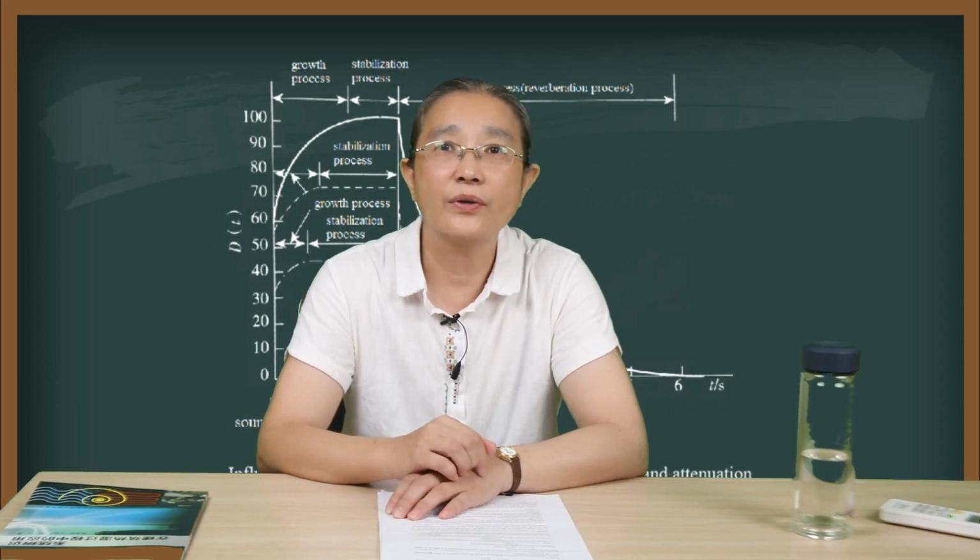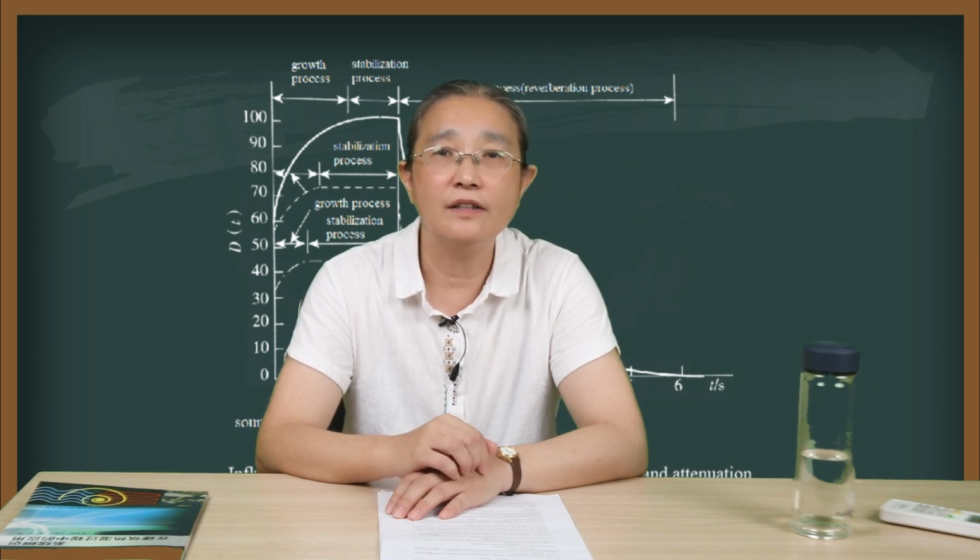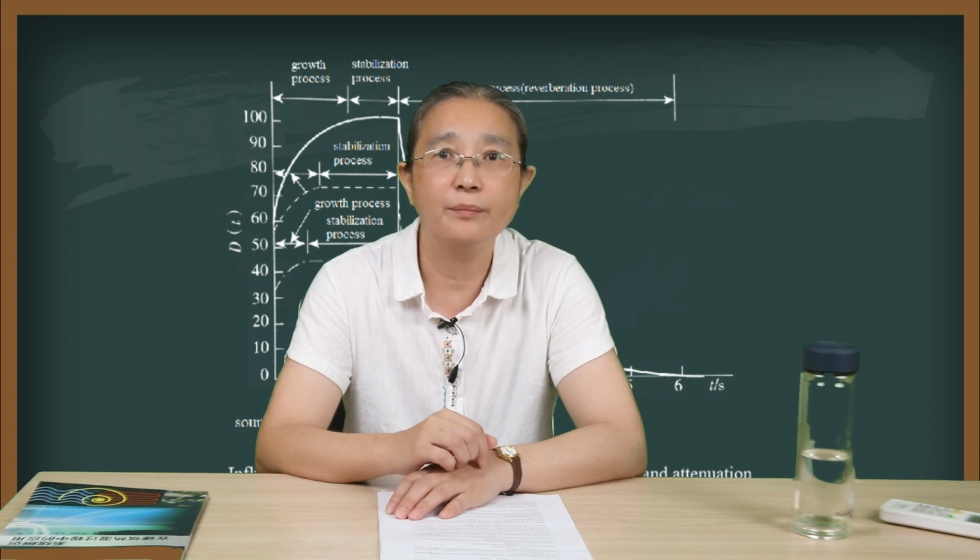You can try to calculate the reverberation time using Eyring's formula for 125 Hz and see the difference between the two calculation results. You can also think about it. What is the appropriate reverberation time for each frequency band? How to use reverberation time for acoustic design? Can noise control take advantage of reverberation time? Should the reverberation time be the same for different types of rooms?